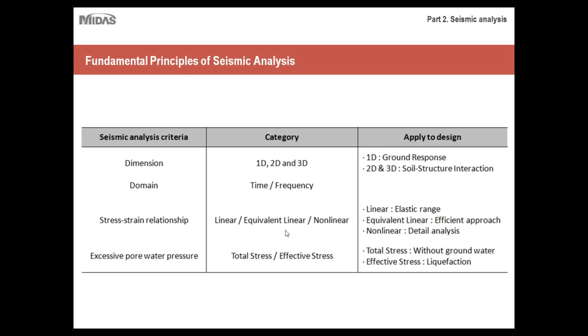I'm sure you all remember the differences between linear and nonlinear behavior in soil. Typically soil behaves in a nonlinear fashion, so this is very important to take into account when you're doing your seismic analysis. We'll go into both linear and equivalent linear analysis processes for soil as they relate to seismic loading. Pore water pressure is also very, very important. Depending on the type of analysis you run, for example, if you were to run an analysis for how soil responds to seismic loading when it's drained versus undrained, the results would be very different.